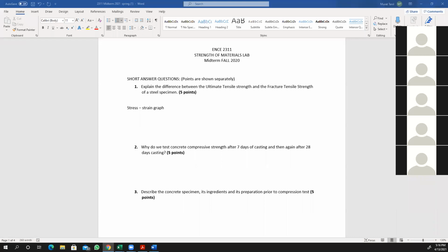Okay, I'm sorry. I have a question. To use a high strength cement, instead of 28 days, you say that it's exactly 3 days, or is it in between 3 to 7 days, or can it be a little more or a little less? Well, there are admixtures that you can use, and you can even get the 14-day strength overnight.